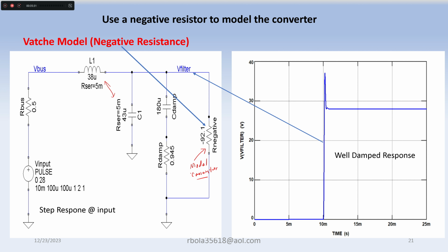On the right you can see how it's very well behaved. The step function starts at 10 milliseconds. It turns on and goes from 0 volts to 28 volts, and you see that it goes up and then comes down, and it's very well damped.